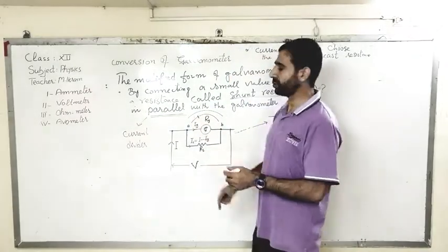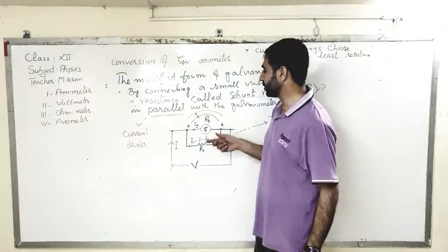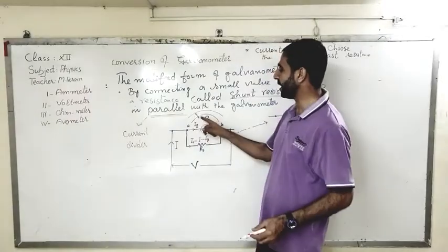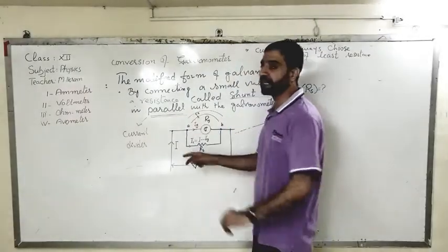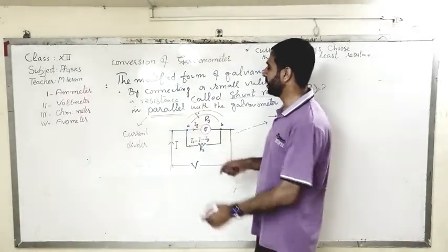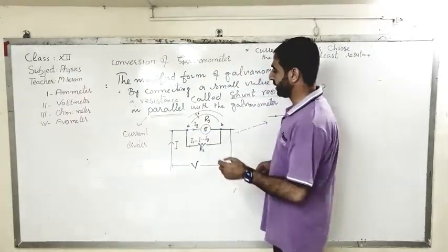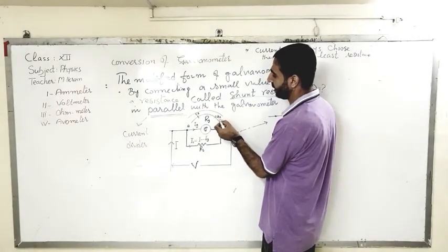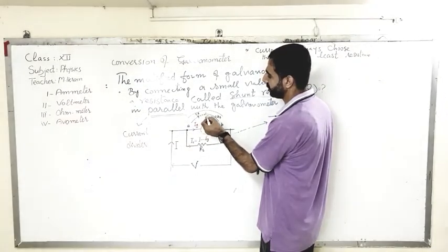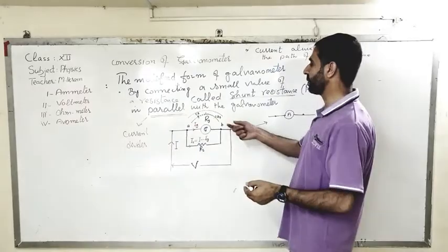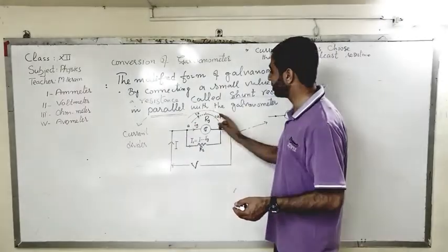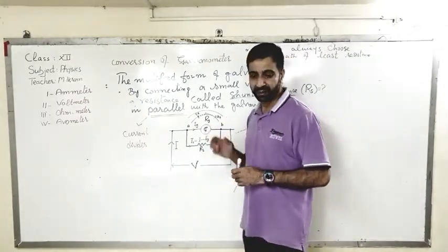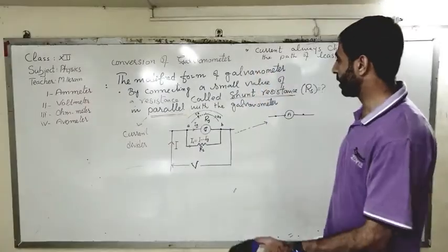So what you will do, you will write 5 ampere, right? We don't care how much is passing through it, but where the galvanometer needle stays, we will mark it as 5 ampere. Then we will do it for 10 ampere. Definitely 10 ampere will be more than 5 ampere, and the galvanometer needle will stay somewhere here, and we will mark it as 10 ampere. This distance is then divided into equal parts, right? So that is what scaling is. Clear?